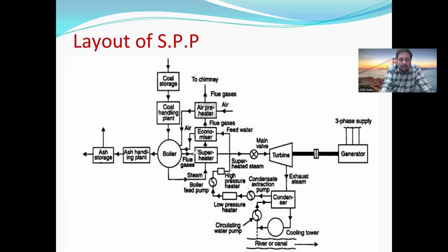Whereas we need to have boiler mountings in order to operate the boiler in a safe manner. We need to use various boiler mountings like pressure gauge, safety valve, steam safety valve, then water level indicator, fusible plug, like that. We have various mountings that will be used for operating the boiler safely, right?